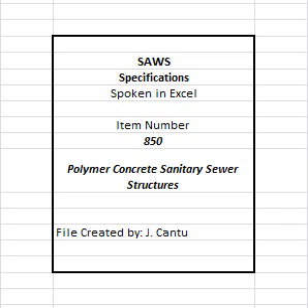9. Thermosetting resin. The resin shall have a minimum deflection temperature of 158 degrees Fahrenheit when tested at 264 psi following test method D648. A. The manufacturer shall use only polyester or vinyl ester resin systems designed for use with this particular application. B. The resin content shall not be less than 7% of the weight of the sample as determined by test method